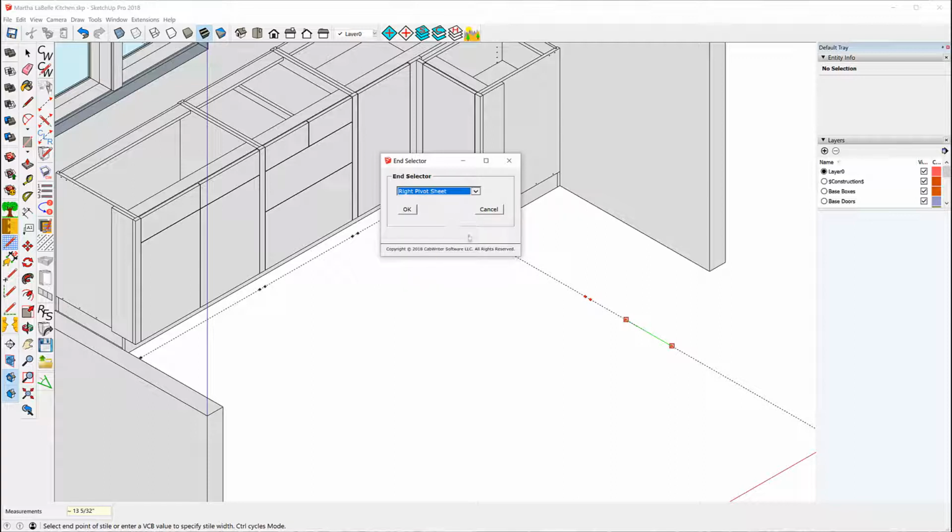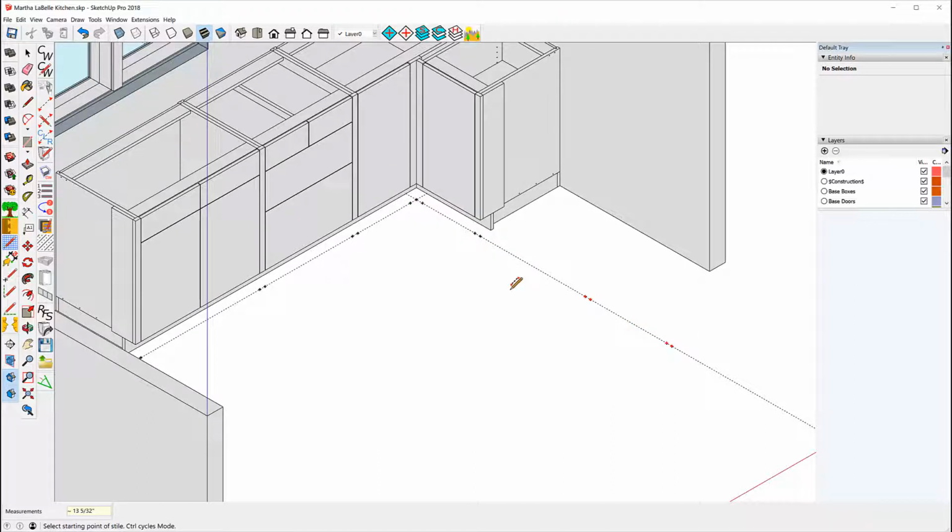In other words, the end panel is going to be a sheet. I'm going to use the distance tool again. A good number for corner cabinets is 14 inches, so I'm going to come out 14 inches. Enter. And come to this side of the pivot point and click. So this is my pivot style, this is my connector style, and this is my left opening style.